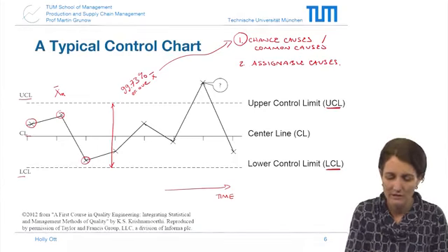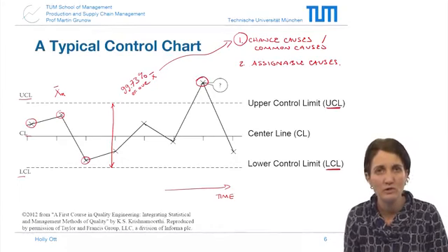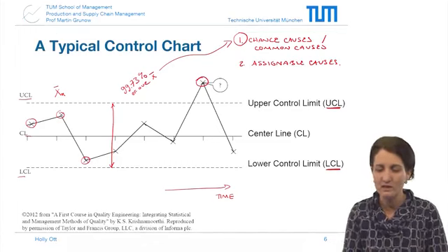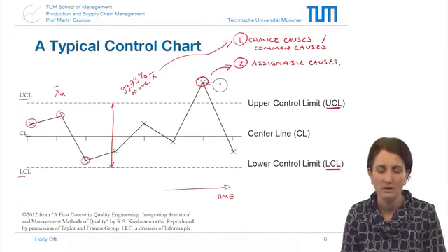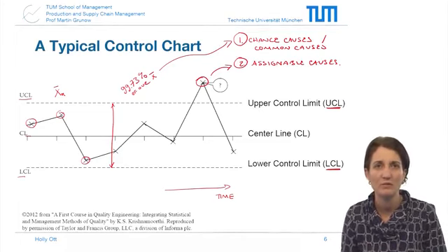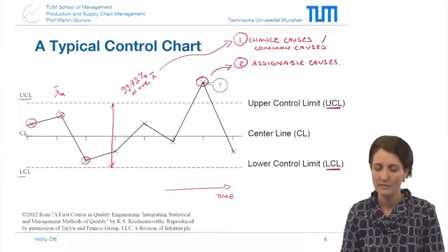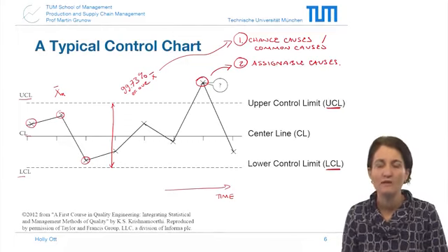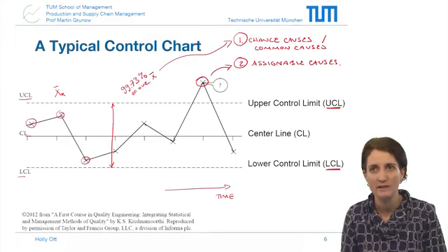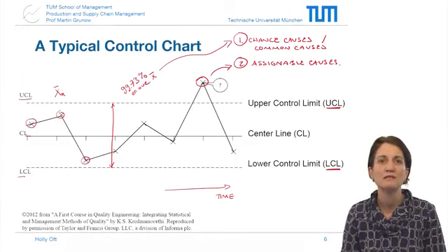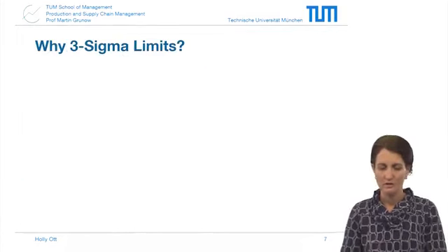However, when one of the points goes out of control, the assumption is that that's a very unusual situation if it were a chance cause, and this is most likely due then to some kind of assignable cause. And that's what the control chart is helping us to identify. So one more time, the control limits, if we use the 3 sigma rule, represent the limits for chance cause variability. And these are computed using data then drawn from the process, which is what we're going to do next.